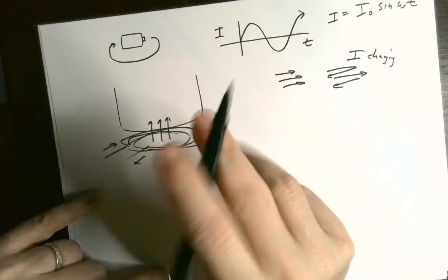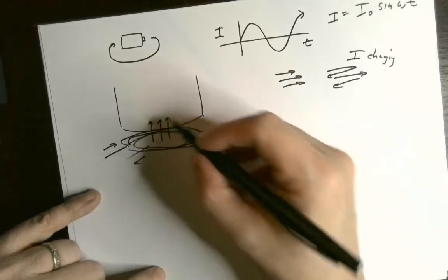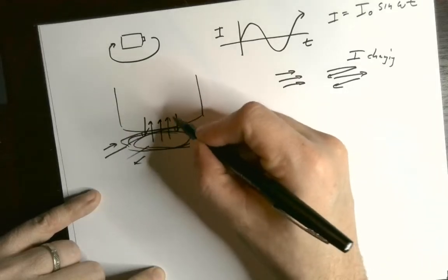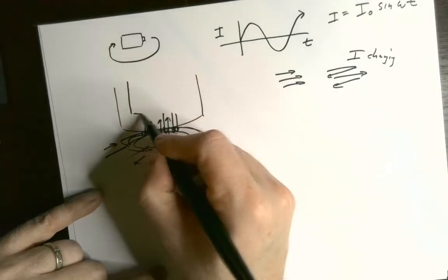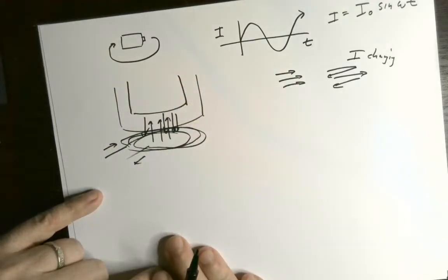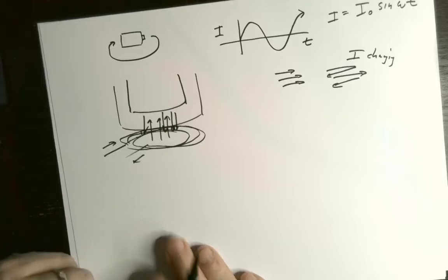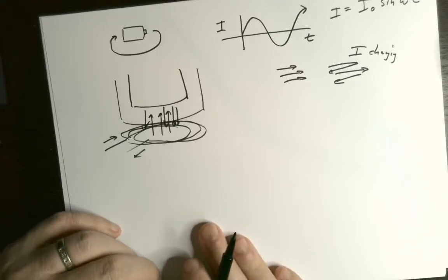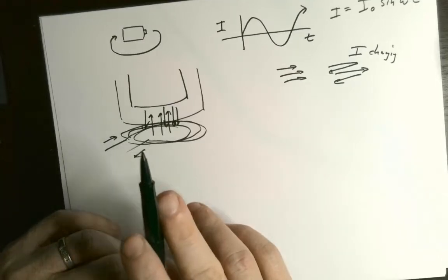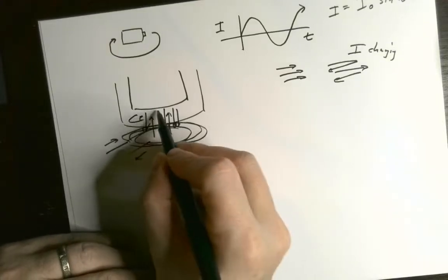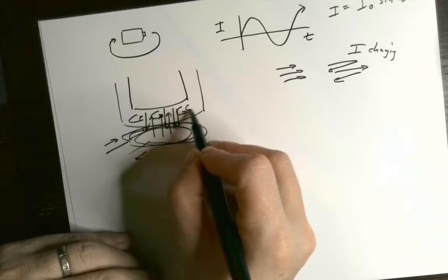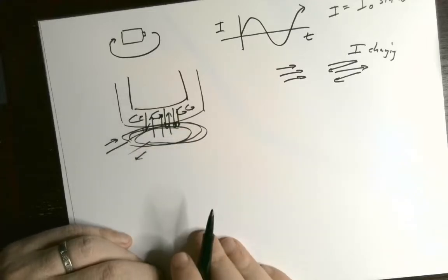That loop of wire creates a magnetic field. The current is constantly changing. The magnetic field is constantly changing from up to down to up to down. If you put something on that object that is made of a conductive material like copper, the magnetic field pointing in one direction and then the other will create eddy currents that will create little magnetic fields of their own.